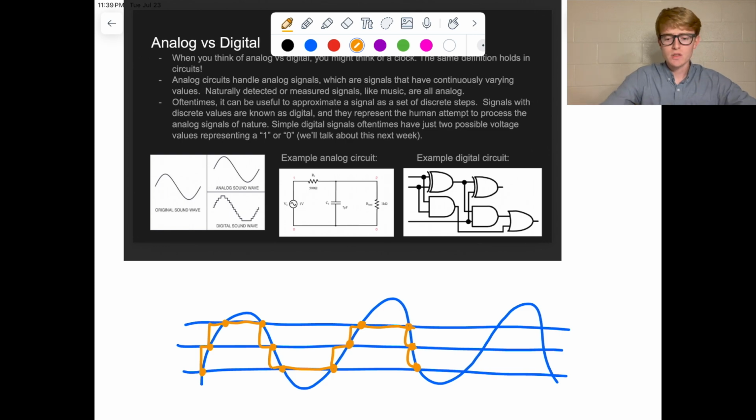So in digital circuits, oftentimes we'll have this concept of binary. So we'll have 1 or 0. Our high will be 1. That might be your high power, so VDD, or to make this concrete, it might be 5 volts. It might be 3.3 volts, whatever high voltage your circuit runs at. That might be your logical 1, and then your logical 0 might be ground. That's the thing we want to think of when we think of the signals passing through a digital circuit. Obviously, analog circuits can have a variety of continuously varying signals input into them.